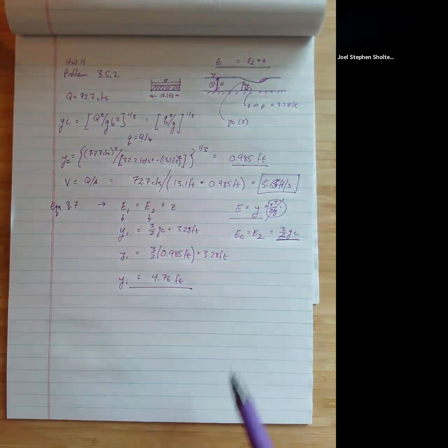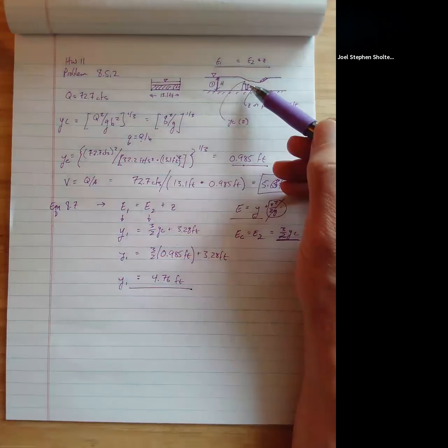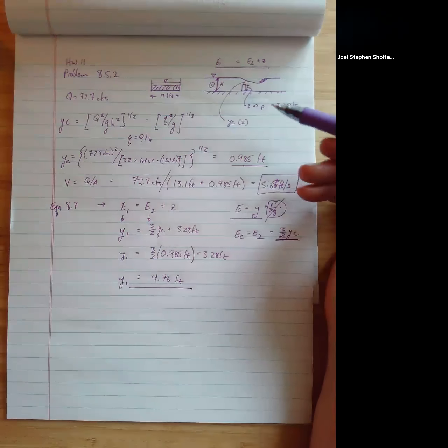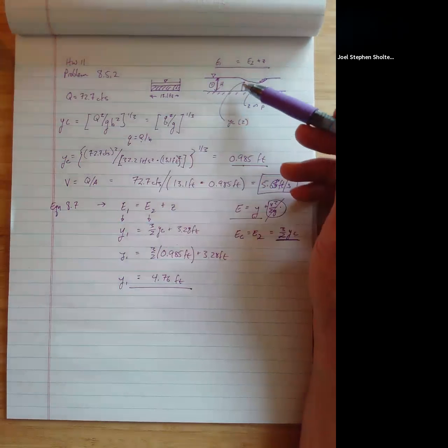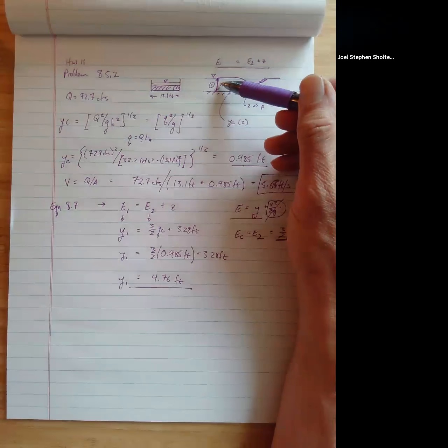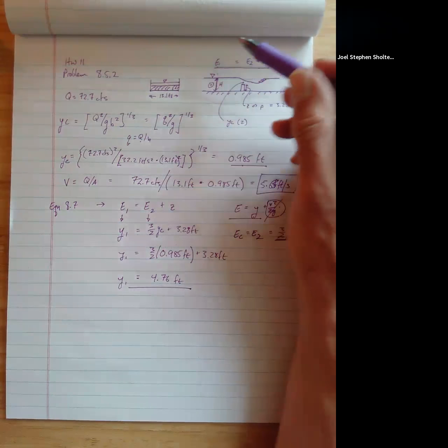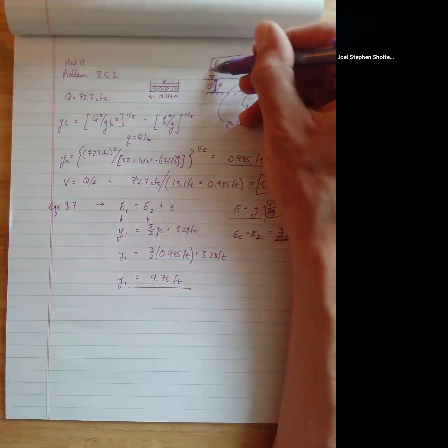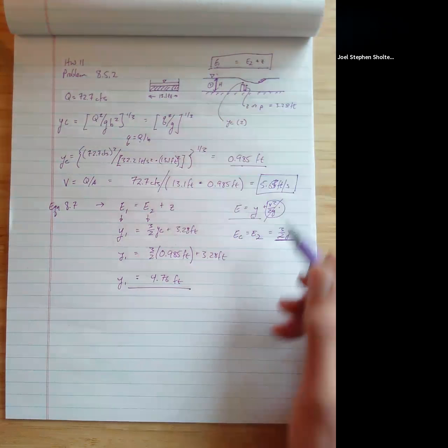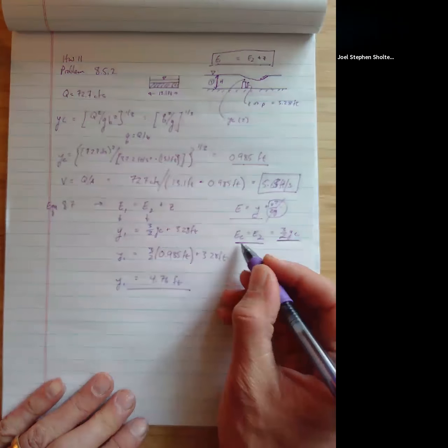So what we did is we just used the assumption of no energy loss over the weir. We knew, because this is what weirs do, that we had critical depth here at the weir. And then because the problem said, let's assume no energy loss and that there's no velocity head over here, well, now we can calculate our flow depth and our energy over here. We relate it to the energy over here. So a big key part of solving this problem is understanding that E1 upstream of the weir is going to be equal to E2 at the weir plus Z, and then E2 is equal to our critical energy at the weir. Because we're at critical depth, that means our energy is critical energy.